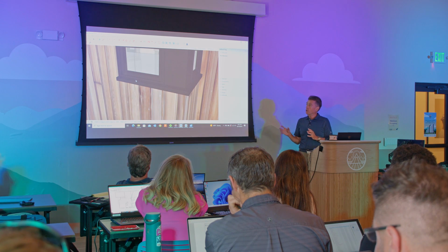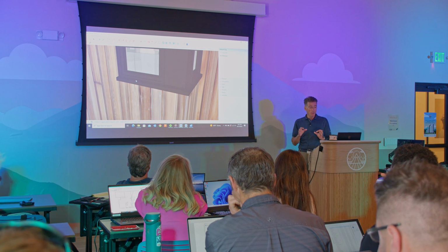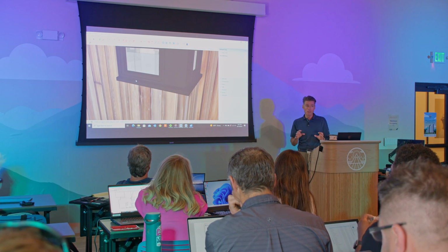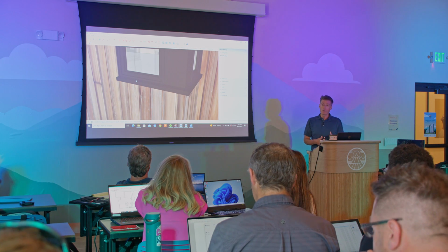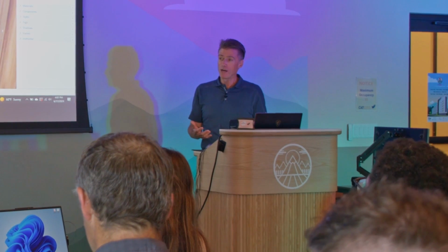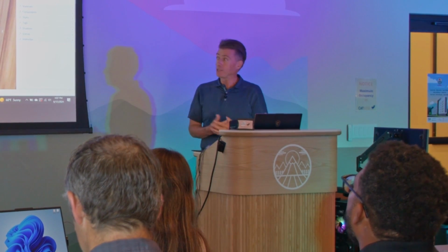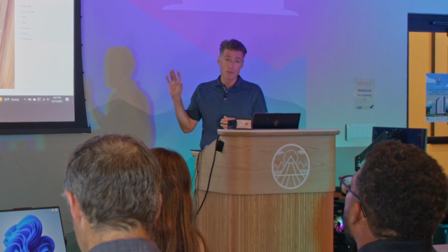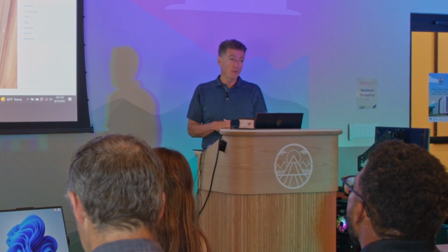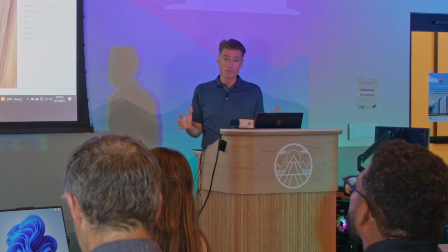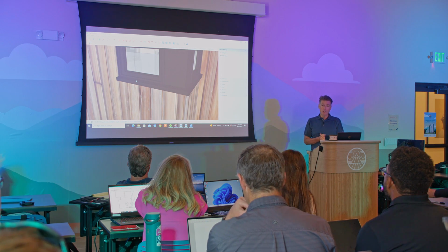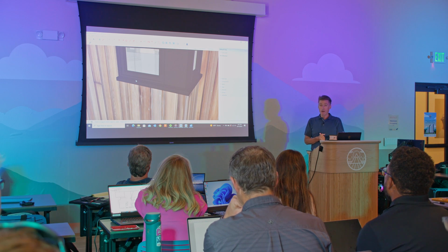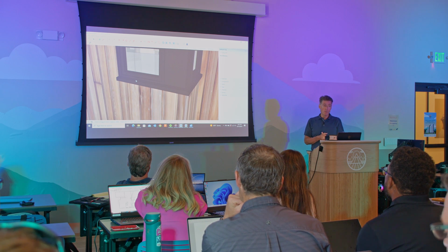The way I'm showing the flashing and the sill, I want it to look this way in the details, but I don't want to try and incorporate that all throughout the model because it would create a massive model file, and there's no need to do that because the drawings that are generated from the house model are going to be at 1/4 inch. So no one's going to see the level of detail anyways. That's also why I'm a big proponent of not showing sheathing or drywall on the interiors in my models because, quite frankly, there's really no need.